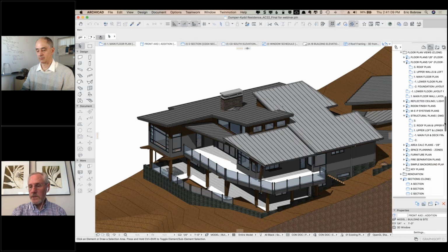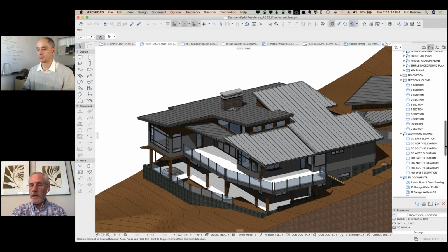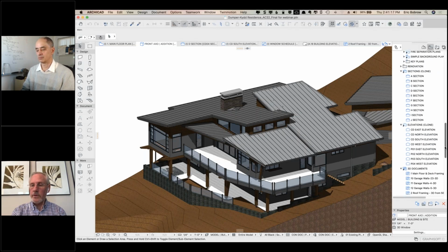the format I stick to. As we were discussing a little bit last night, I do add a couple of layers if I need extra layers to show certain things that I put in, because I do work out most of the framing. It's how I learned to do it, and it's a good exercise for me. I don't put all the studs in the walls, but I do put lintels in. I know where they are, and I work all the loads down from the roof all the way to the foundation. So there's going to be no surprises that I don't have bearing somewhere.